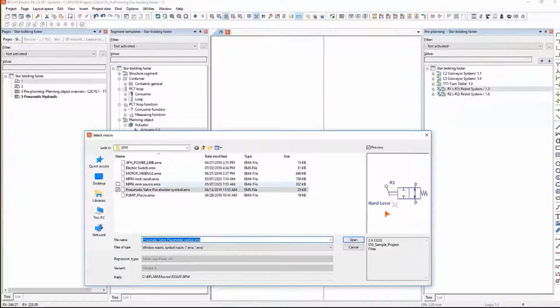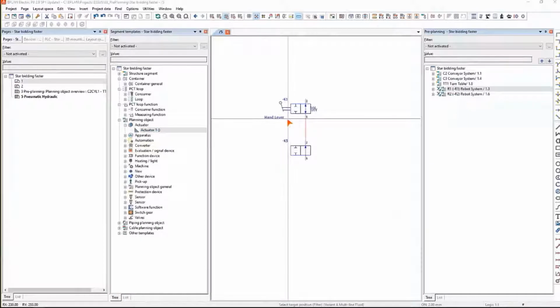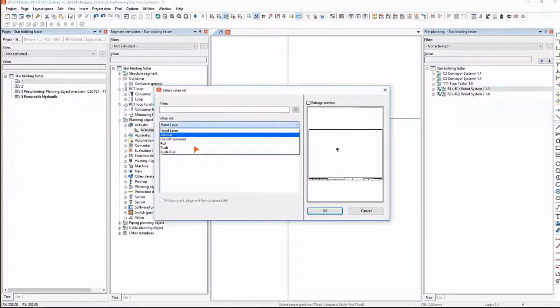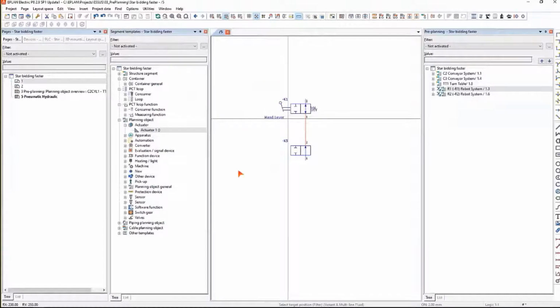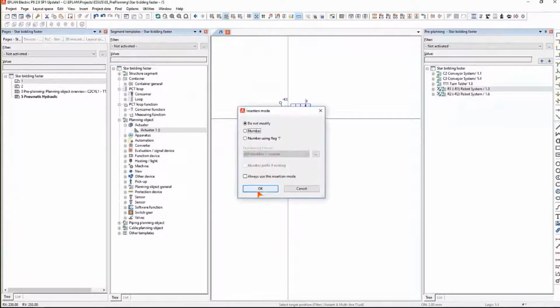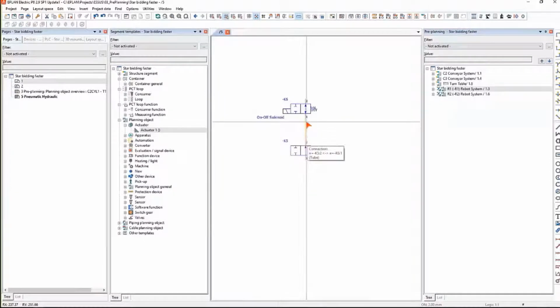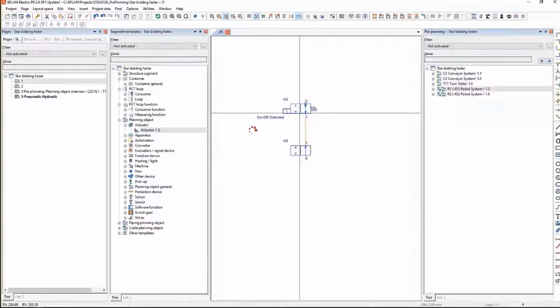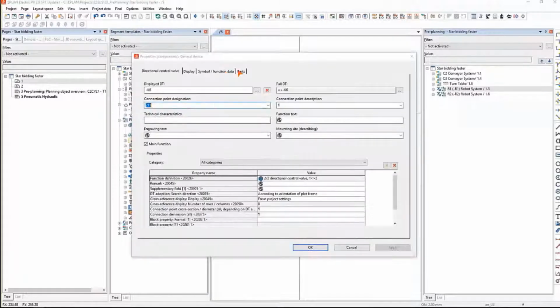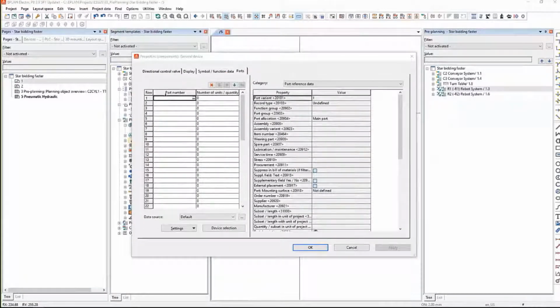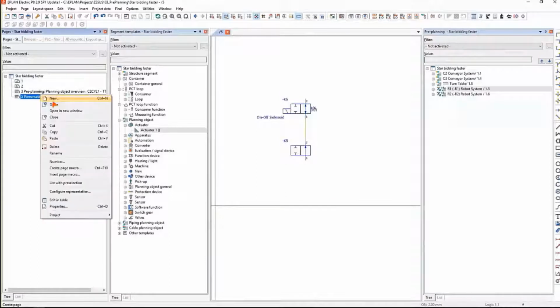In this case, I'm just going to place a valve, and then I can select what type of solenoid I'm going to use for it, and then it's going to adapt the symbology associated with it. So now this is not a wire, it's considered a tube because it's carrying air. But behind that symbol, you can also add your part numbers, and you can store all of your information regarding your bill of materials, as well as your components for the 3D layouts. Then you have your Electric P8, which is your electrical circuitry.